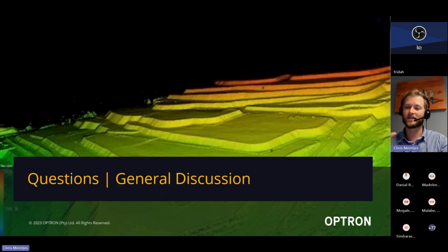So if you're going to be scanning buildings, something I didn't touch on in this webinar, just time constraints. If you're going to be scanning buildings or structures and you want to model that into IFC models and take that into Revit or SketchUp or Tekla or all those 3D BIM software packages, then RealWorks is more ahead of TBC in that.